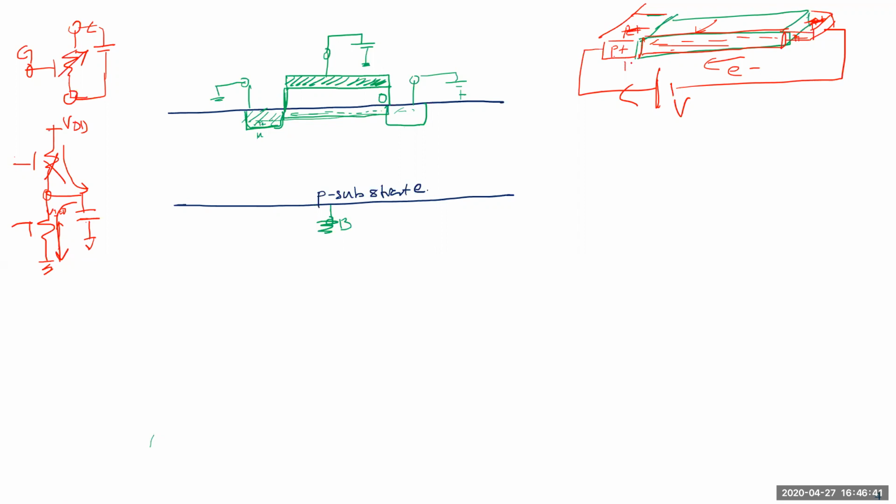Right. So you're saying basically it's like this, two reverse bias diodes, right? Yes, sir. So that's a way to look at it circuit-wise as well. Okay. And from an electron-hole perspective, the only mode of transport here is electrons, right? There are no holes here, very few holes. The question is, for current to flow in the circuit, it has to make it through this to the battery back here. That's the whole idea.